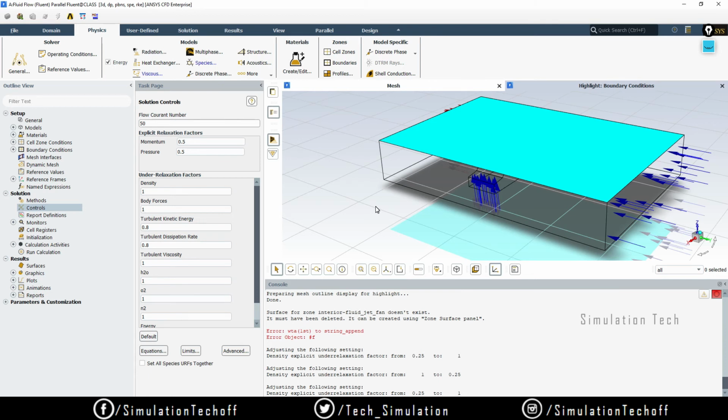There is no relaxation involved in the convergence, which may make your convergence process too complicated. If I give a factor of 50 or 100, some relaxation may be done in the convergence process, so some assumptions may be made to make the problem easier to solve. So I'll give the factor of 50. If you want to give a higher number of values, you can. That is not an issue.